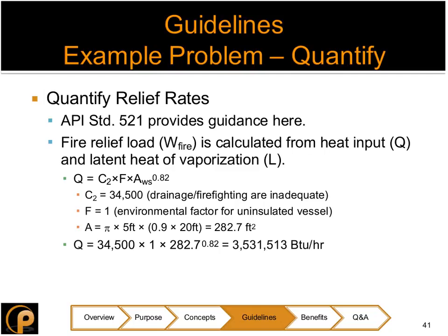Okay, thank you. If I have a system pressurized with a centrifugal pump, known deadhead pressure less than vessel MAWP, is a PSV still required on the vessel? It doesn't seem like it, at least not for the blocked pump outlet case. That was one of the examples that I gave earlier about how to qualify an overpressure. If your pump at the deadhead position with the highest suction pressure can't reach MAWP, then there's no overpressure.